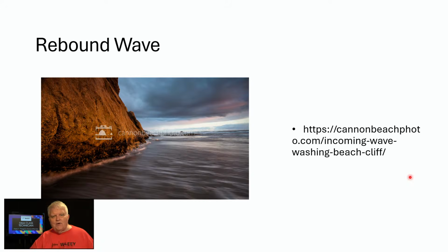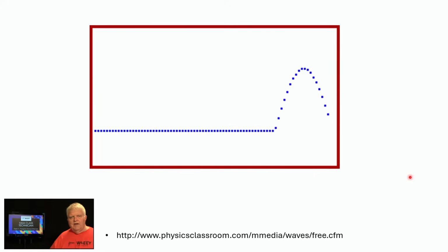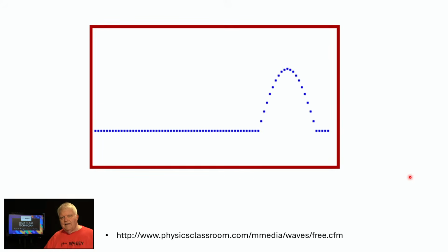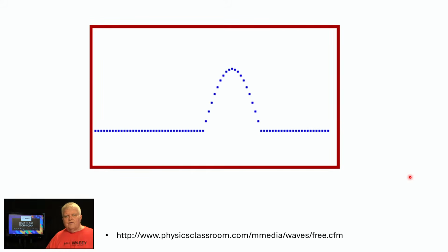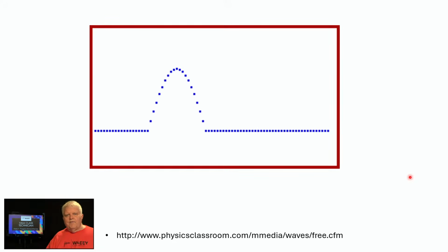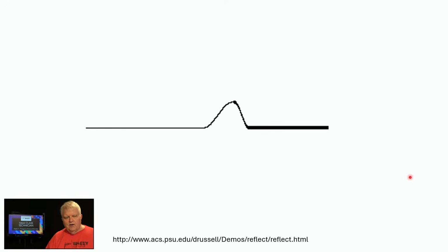Well, the same kind of energy bounce back goes on in a transmission line. A radio frequency signal comes from the transmitter, it's sent out over the feed line, it hits an antenna or a mismatch at the other end. This is the worst case. This is saying that all of the energy, see that big hump that represents energy, is going out from the transmitter and it's all being reflected back toward the transmitter. Nothing is being radiated. Here we have a similar situation where some of the energy is being radiated, see it's going off to the right, but some of it is being reflected back.